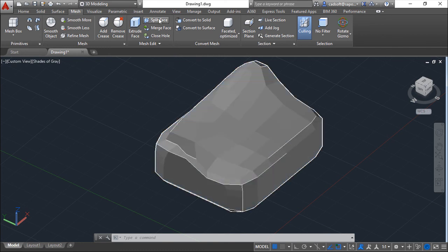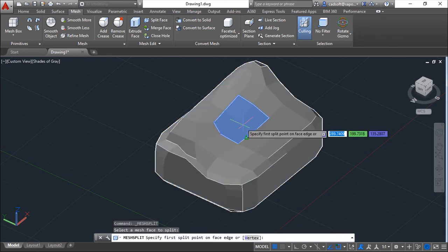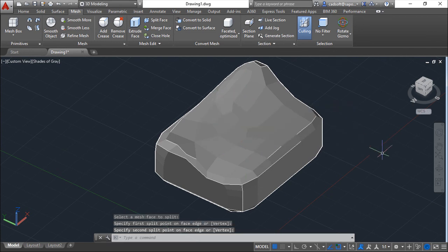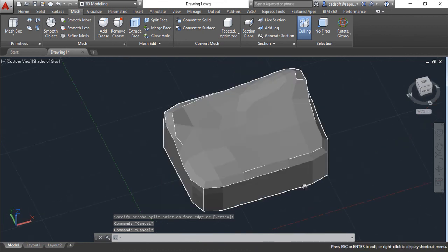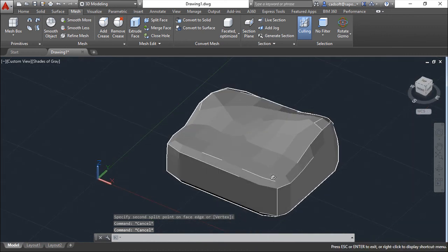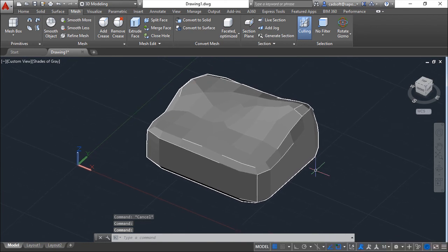And we can have a split face, where you choose one face, you choose a point or something, and an area which will divide your face. So these are some of the possibilities when working with the addition of the meshes, in particular the faces and the edges.